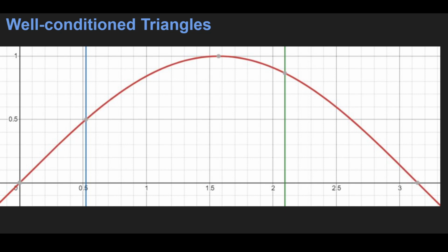Now you might say, why are we limited to 120 degrees? Remember that we are talking about single angles here, and we have a triangle, right? If you have 120 degrees for one angle, that means you only have 60 degrees left for the other two angles. Since we have a limit of 30 degrees, we have to limit it to 120, right? 180 minus 120 is 60, divided by 2 is our limit, 30 degrees, okay? So you have to limit your angles from 30 to 120.